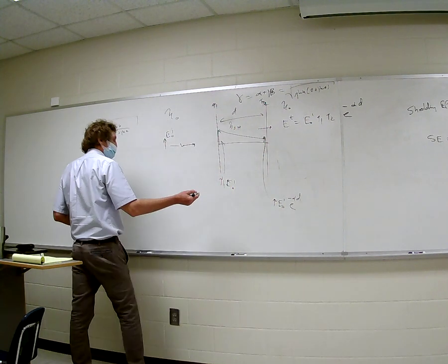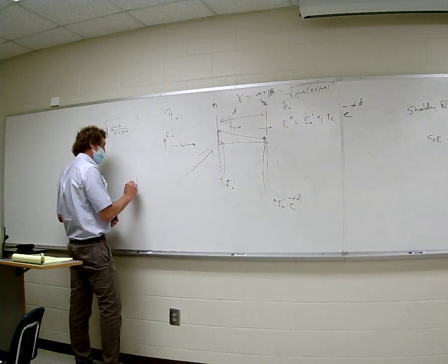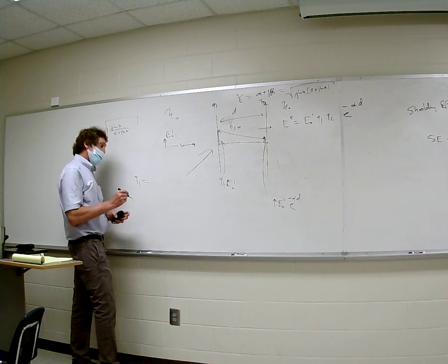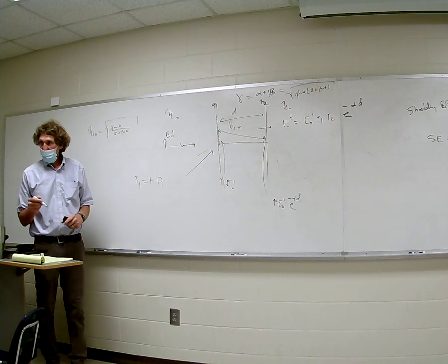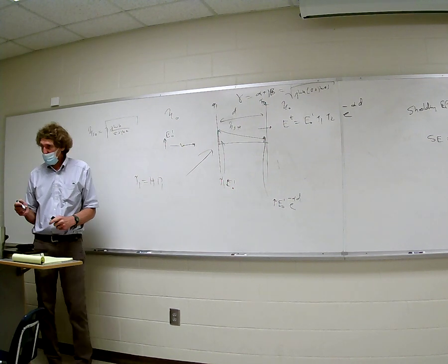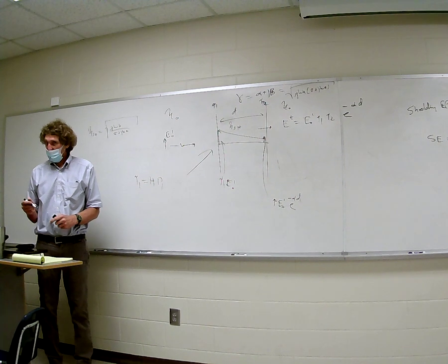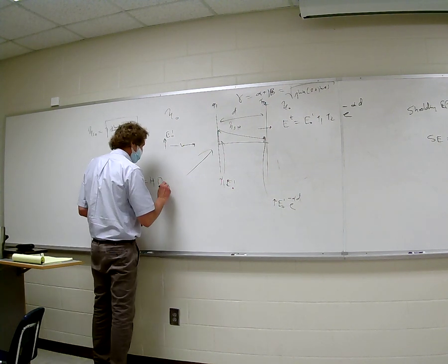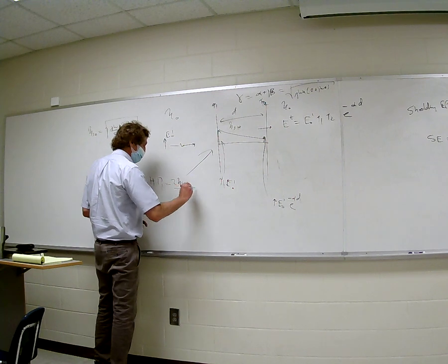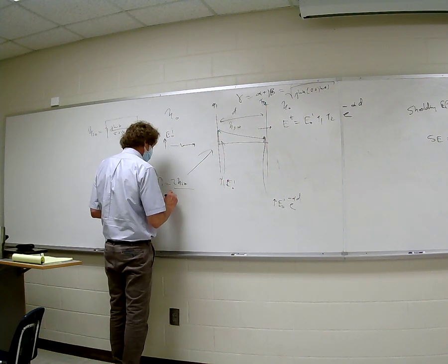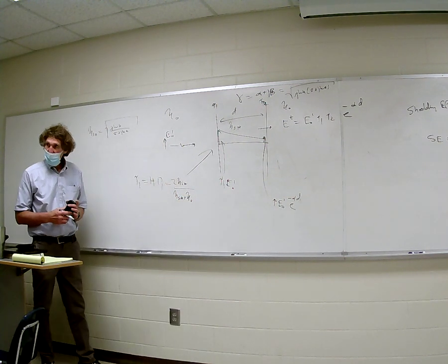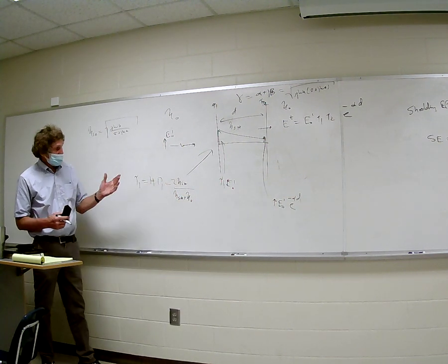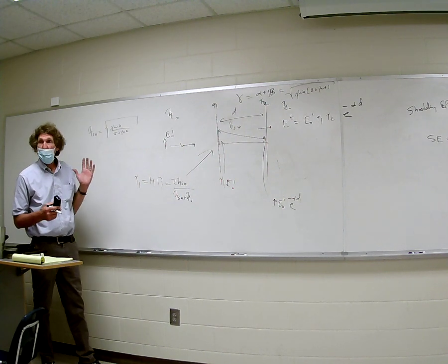Now, do you remember what the transmission coefficient is right here, tau 1? Anyone? Well, it's 1 minus the reflection coefficient of region 1, or I mean 1 plus reflection coefficient, right? Do you remember that? And what is it really? Well, it's 2 eta shield, the value of the impedance you're going into, over eta shield plus eta naught, right? Isn't that the transmission coefficient? And realize when eta shield is equal to eta naught, it's 1. Everything's transmitted. There's no reflection.